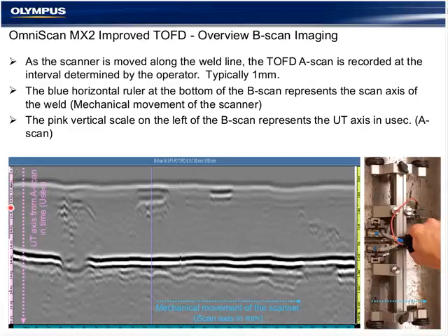It represents the A-scan time base, and we will set our range so that we are covering the lateral wave and approximately 1 microsecond before the lateral wave, and we will either include the back wall or not, depending on the need, the procedure, and the preference. In this case, the mode converted shear wave is not being displayed, but the back wall is.